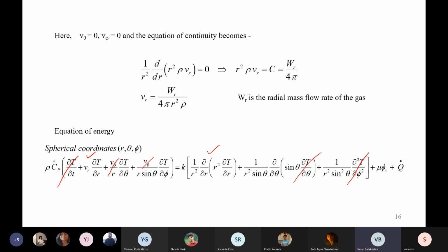So then I guess we can take it to be equal to 0. The viscous dissipation term would not be there since the flow rate of air is rather small, and nothing has been mentioned about the gap between the two spheres, so it could be significant. Unless they are very close to each other, there is not going to be any effect of viscous dissipation.